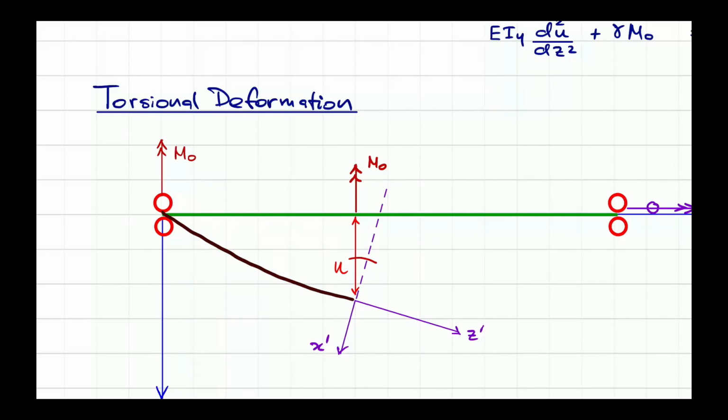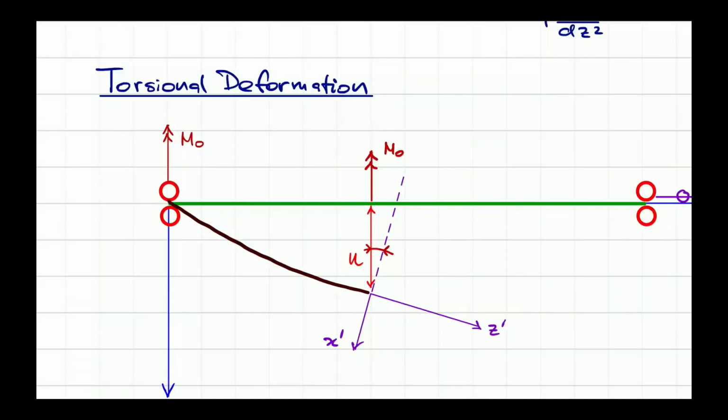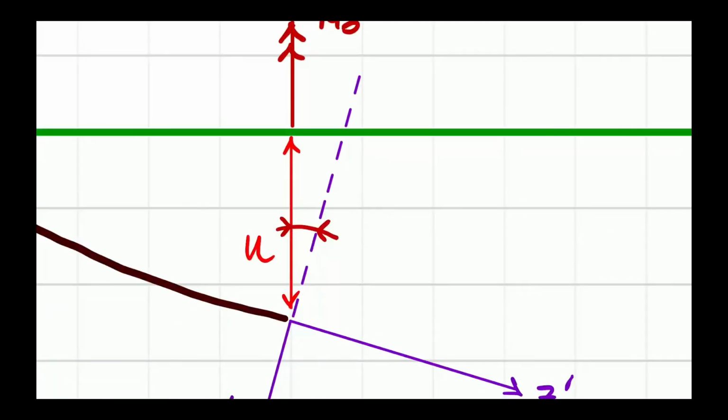We have the reason why we look at the U, why I wrote out the U. The U explains to us the deformed profile that you can see from the top view. So the angle of this deformed profile, I mean the slope, right? The slope is the du dz. So this angle over here is given by du dz.